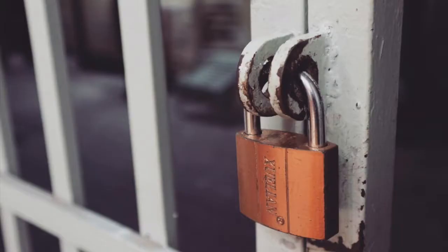The U-shape geometry is also selected because it's easy to form through the bending of a rod, and is also the ideal shape for locking because its shape allows it to be slid into latches and used in many different situations. The bar length of 15 centimeters was chosen such that the shackle was not too small, but also not so large as to be expensive.